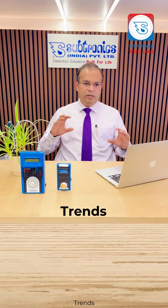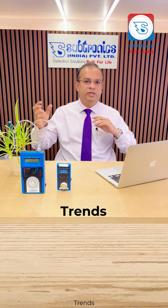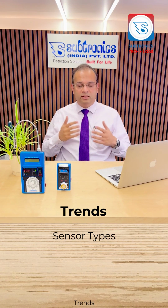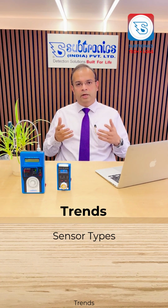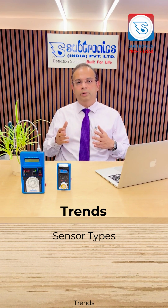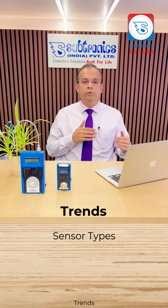So usually whenever you go for gas detection systems, make sure that these points are covered. Trends also depend on the kind of sensors that you're using in the detectors. Now these sensors, we always recommend based on the type of gas that you want, right? For example, if you have an LEL sensor, we would recommend a semiconductor sensor or catalytic leak sensor. But if the same thing is a toxic gas, say for example ammonia, then we would definitely recommend an electrochemical sensor, which has a very high selectivity towards that particular gas and can measure very low concentrations also.